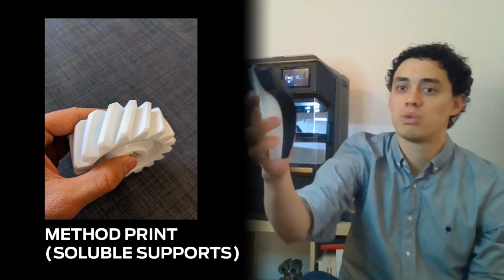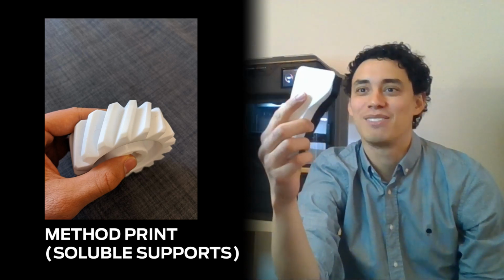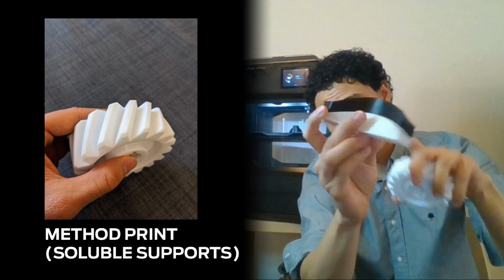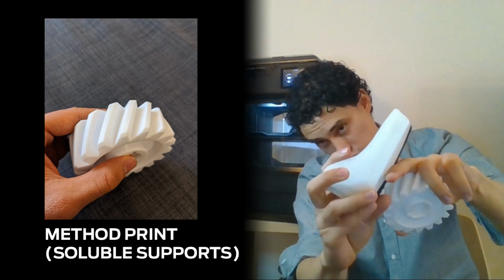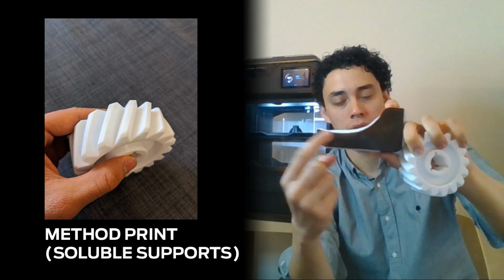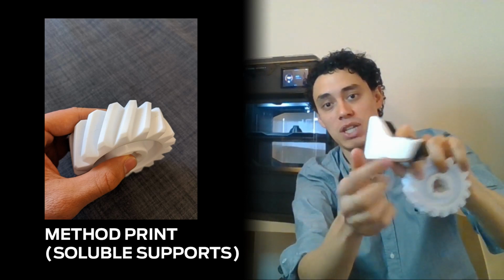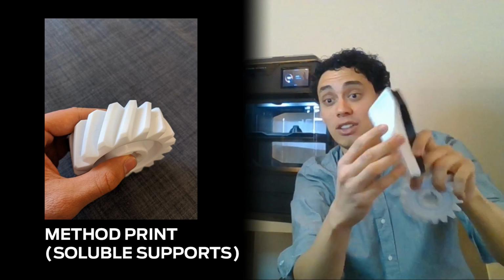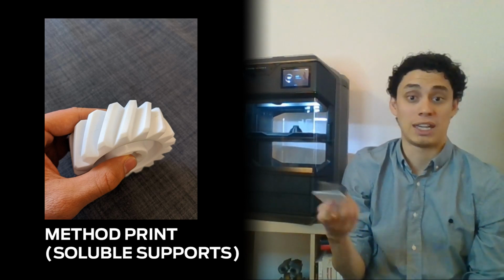So this is an actual part that I printed yesterday. It's kind of a new material. I cannot talk about it yet. I'll mention it in a second. But it's using SR30 support. So this white element is a support structure. This part is hollow. It's kind of a door handle for a car, right? So the part itself is hollow inside, and because of that, it requires support material to hold that part up. These supports, I just need to dunk them in water with the solution for SR30 and they go away, right?